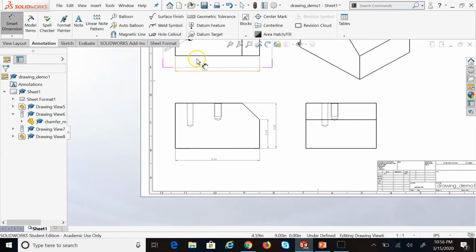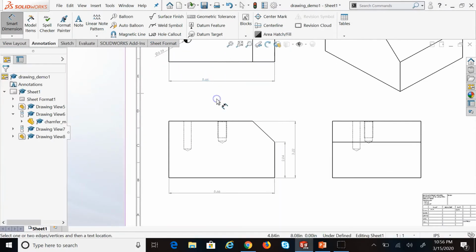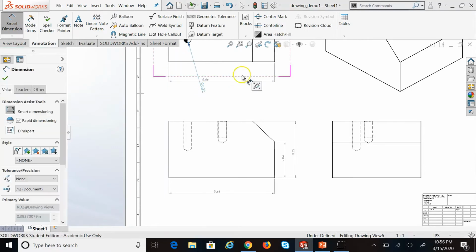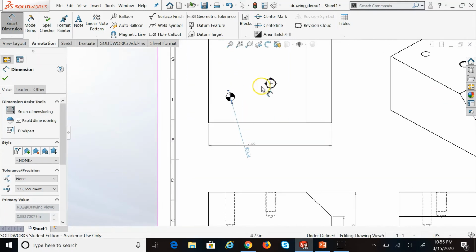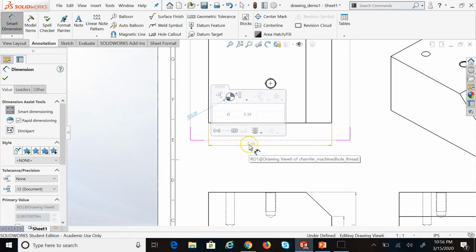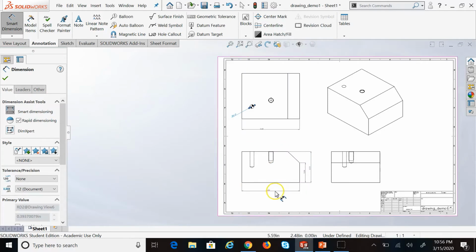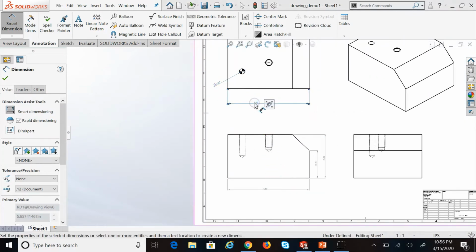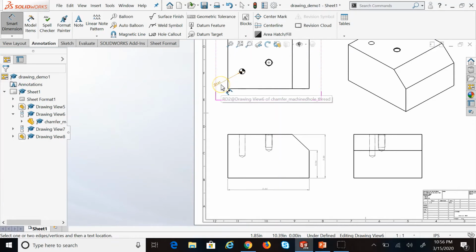So here, if I come back here, by the way, this guy is a redundancy, but we learned not to intersect. In order to avoid intersect, I'm not going to put that radial dimension, that diameter inside. So I'm not going to do this. Radial dimensions, which are the dimensions for arcs, should also be put outside, where no intersection with linear dimensions is possible. So first of all, here in this case, this 566 is a redundancy, so I would get rid of that, and I put this diameter outside.